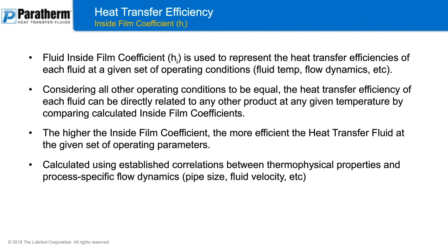The next key point was heat transfer efficiency. Now, these are things that you need to take in comparison with one fluid to another. Keep in mind, that's what we mean by benchmarking. You're looking at two different fluids. Heat transfer efficiency is where you can take the data sheet of product A and the data sheet of product B, put them together and say, what's going to give me the best heat transfer efficiency? Well, how do you do that? Well, we use the inside film coefficient, this H sub I designation, to represent heat transfer efficiency at any given set of operations.